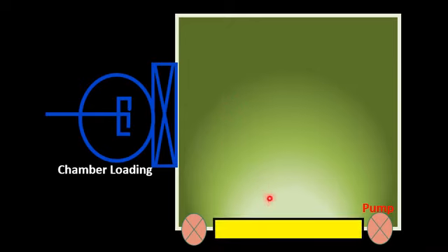Inside the reaction chamber of molecular beam epitaxy, there is a stage, okay, and on this stage usually the source material is present in the crucible of the molecular beam epitaxy. So this is the source material. The source material is a material which we want to deposit, okay. Source material is also present in the chamber loading setup, and it is also present inside the MBE system for deposition. So the source material which is present in the chamber loading system is usually not used for deposition.